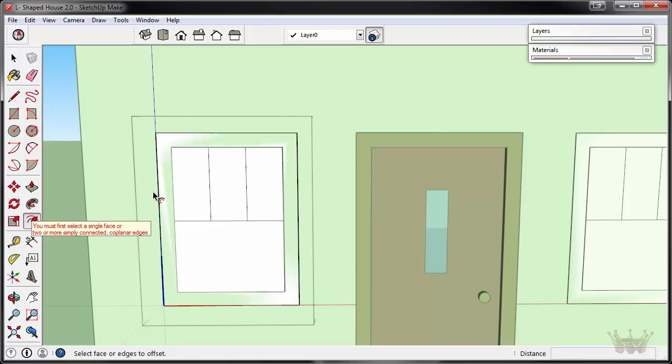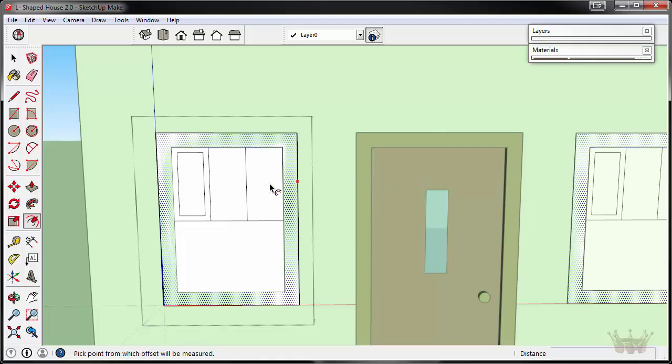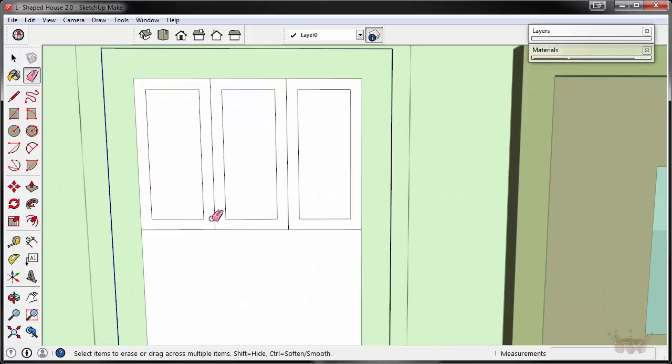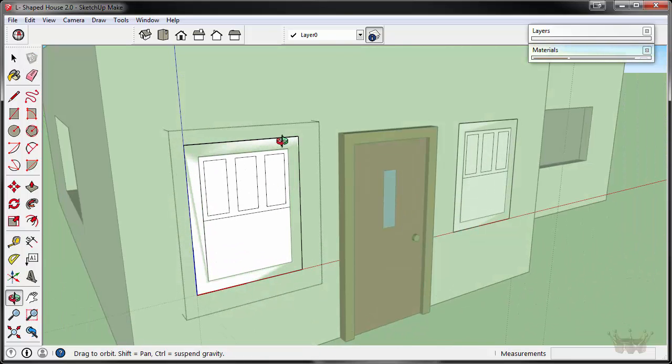Let's take the offset tool and carefully in each side create ourselves an offset. We're going to use an offset distance of 1.5 inches. Notice that over here this component has changed as well. Remember that the offset tool remembers the last unit of measure, so if we double click on the remaining window panes, they will all become the same value. Let's delete the middle lines, giving us 3 window panes.